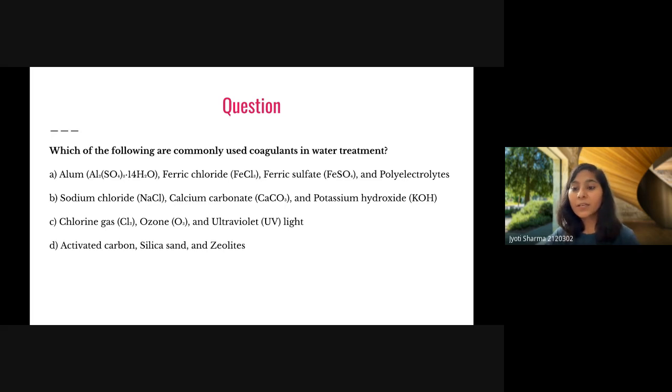Acidic is because of sulfuric acid, because sulfuric acid will be formed in your surface water. So sulfuric acid will give you the acidic nature of the water. That's why whenever we have to add this alum coagulant in the water, we have to add bicarbonate so that pH can be maintained, because bicarbonate is basic in nature. So this will be basic, and then we have alum that may create sulfuric acid, so that's how it will neutralize.